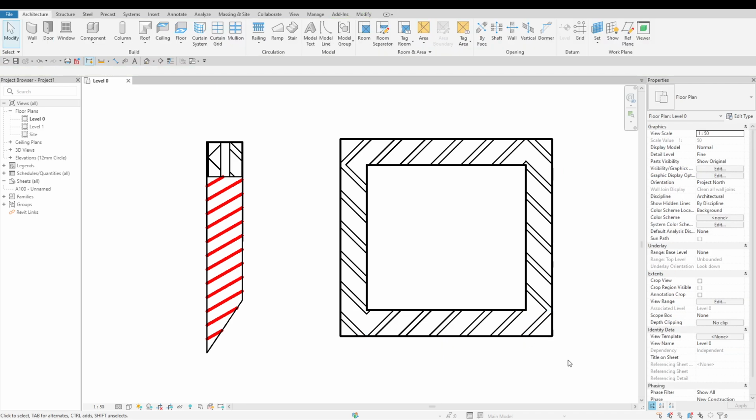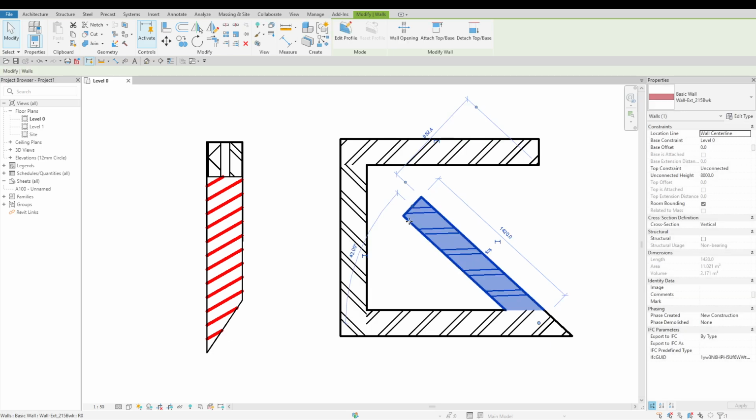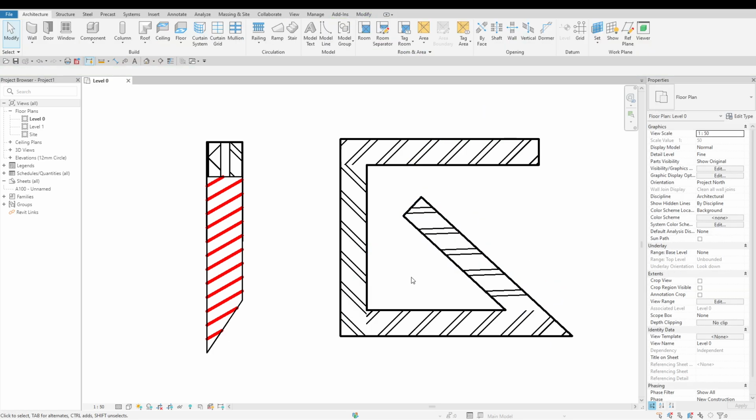Revit provides 3 orientation options when applying a drafting fill pattern to host layers: orient to view, align with element, keep readable. Align with element. The pattern follows the orientation of the host element. This approach is especially useful when working with elements that are not orthogonal or are placed at varying angles, such as angled walls or sloped roofs. Revit automatically computes a suitable origin point for the pattern based on the host geometry.